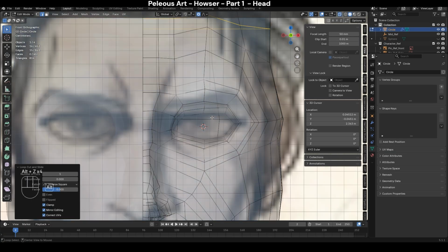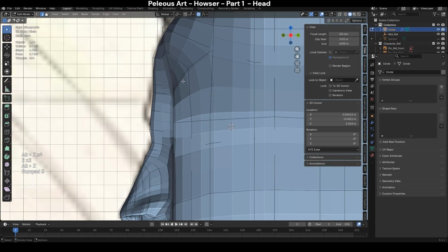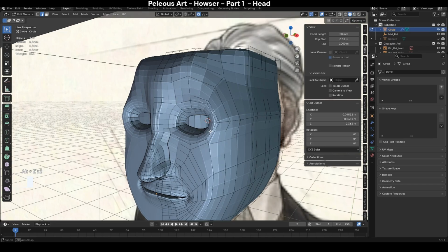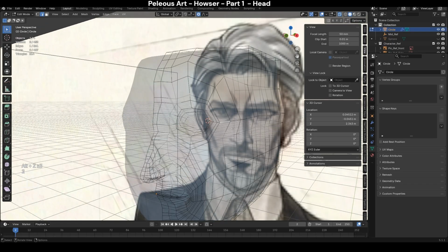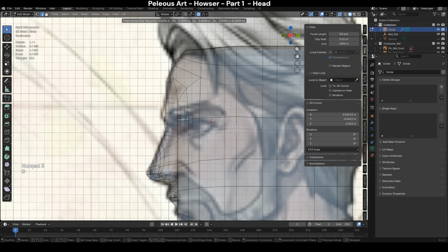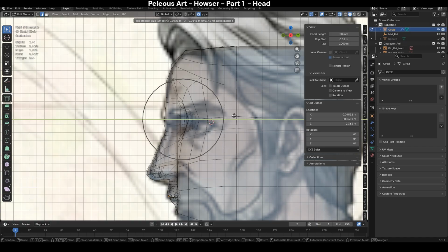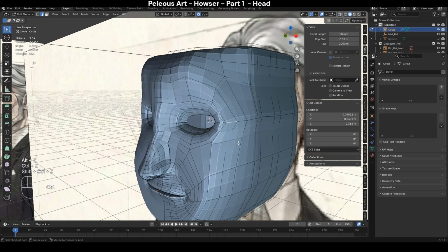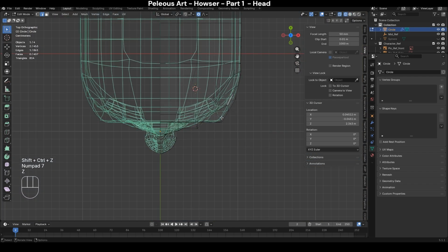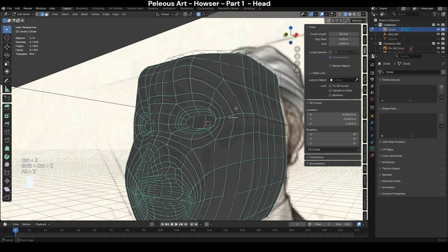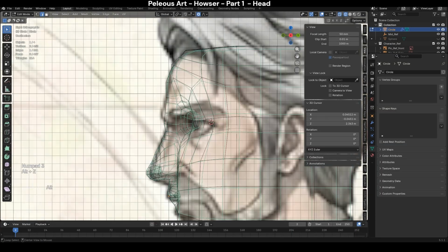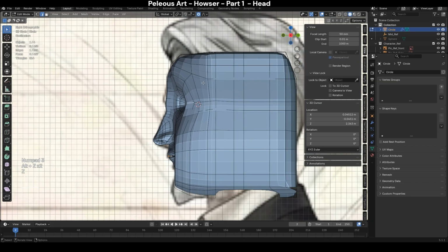And maybe the eyes, we can start working on the eyes. So go to the side, select the edge, the side of the face, and pull it on the Y. Okay, not too much, and very carefully, as you can see. Just pull it enough to be round and not a sharp corner. You can see how the loop proceeds.